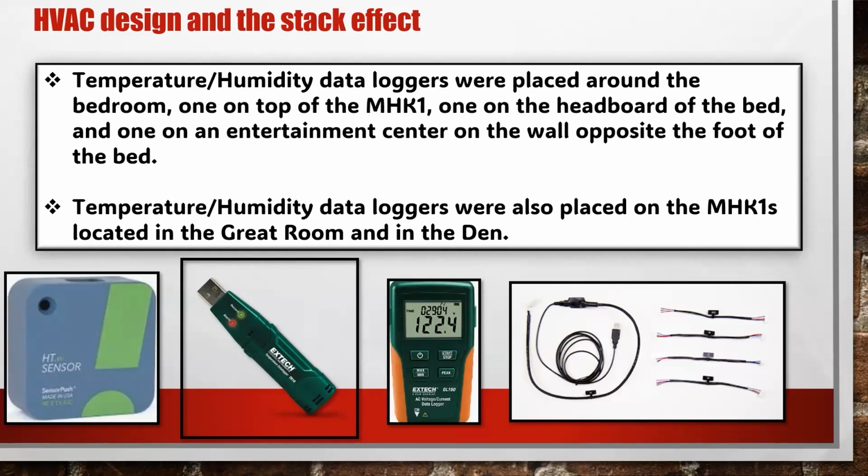I also wanted to see every time the indoor unit did what we call an overheat protection scheme. You probably have noticed in multi-zone units, if the outdoor unit's running and the particular indoor unit is not running, occasionally, even if the unit's off, the louvers might open up and the fan blow for a minute. The coil got too warm and the unit's trying to cool it off.